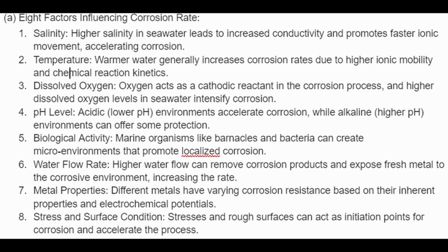3. Dissolved oxygen. Oxygen acts as a cathodic reactant in the corrosion process, and higher dissolved oxygen levels in seawater intensify corrosion. 4. pH level. Acidic, lower pH environments accelerate corrosion, while alkaline, higher pH environments can offer some protection.